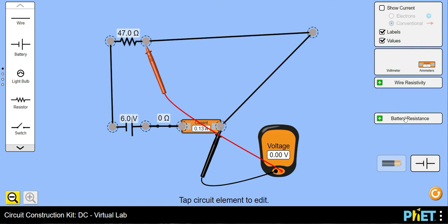We also have battery resistance. Battery resistance is a funny term. A battery is not a piece of wire. A battery is a tube packed with some kind of chemicals undergoing a reaction that deliver electrons. If you attach wires to either end of the battery, it'll establish a voltage along that path. For alkaline batteries, that's 1.5 volts, and there's no way to change that other than using up the battery. Even 9-volt batteries, if you open them up, you'll find six 1.5 volt cells, not D cells, quadruple A cells.